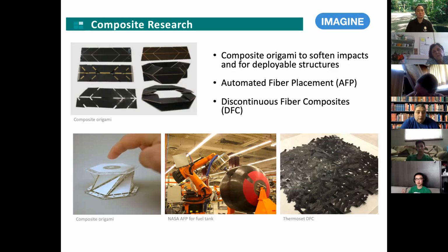Another aspect we're researching now is recycling, because with all these demands for carbon fiber, there's going to be a lot more waste. You'll have sheets of carbon fiber with just a hole cut out of them. So all the scrap waste on the sides can be cut up into these platelets and made into whatever, rather than how they typically get rid of the resin on the fibers now, by burning it or putting it into some sort of acid like sulfuric acid, which could be pretty dangerous. So yeah.